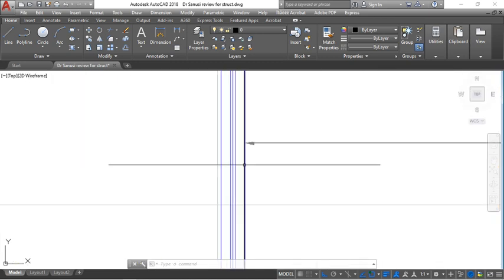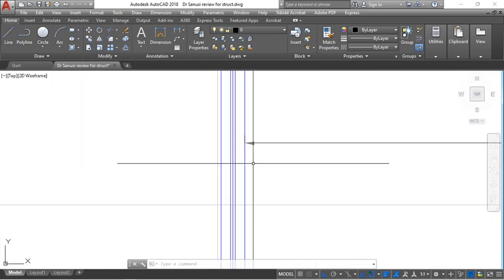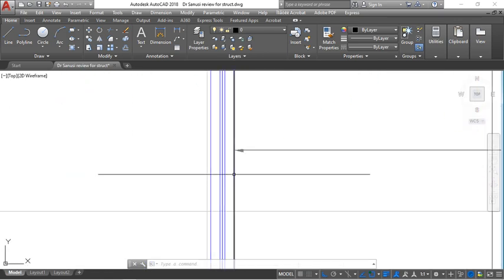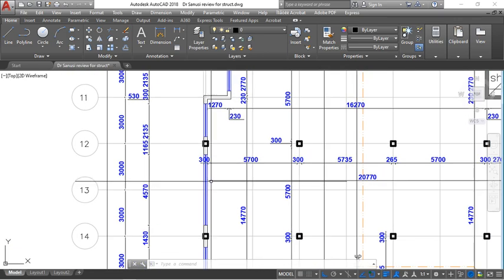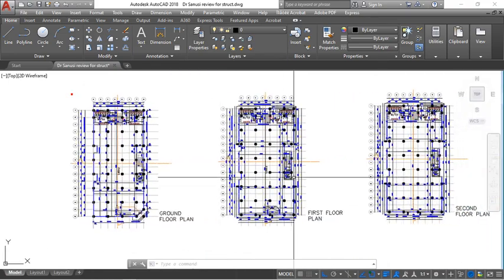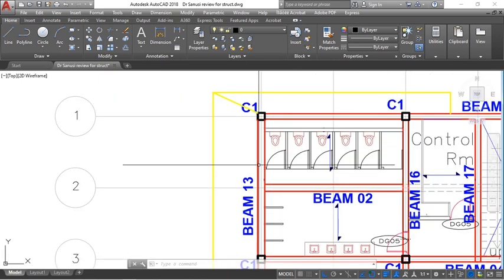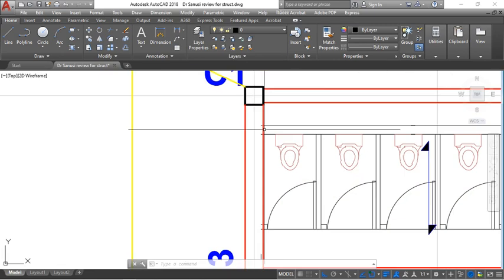No, there's nothing like blinding your wall. If you follow construction technique, have blinding, have foundation, and the recommended thickness of foundation for your wall is 225 minimum. So in practice, we have people constructing 75 mm. They will now say it's blinding for the foundation wall, and they start placing.